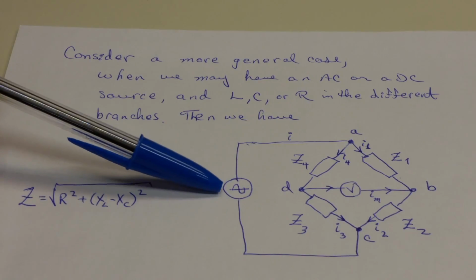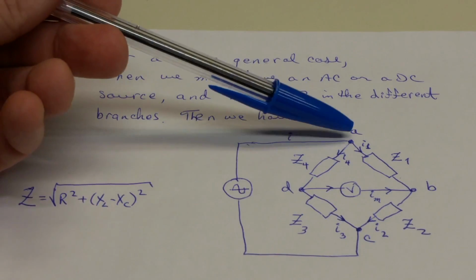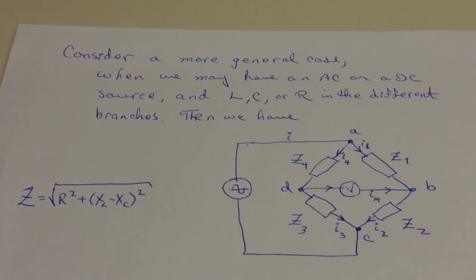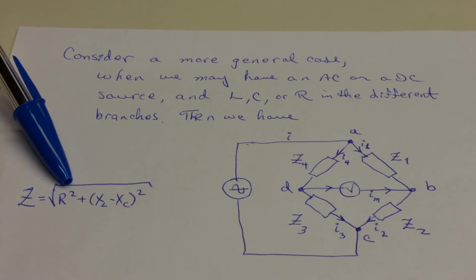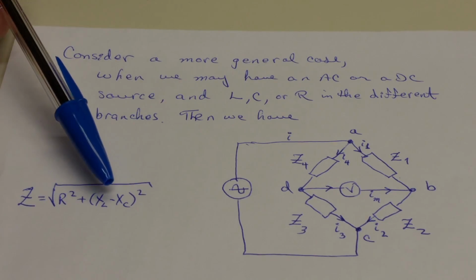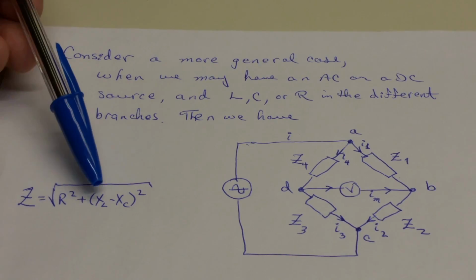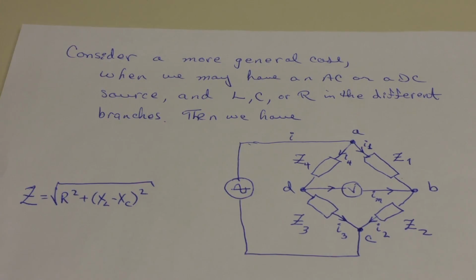And instead of applying a DC across the two nodes of the circuit, I'm going to feed it with an alternating current of a known frequency. So the impedances are nothing more than a function of the resistance and the reactive elements, which might be an inductive reactance or a capacitive reactance, or a combination of the two in general.